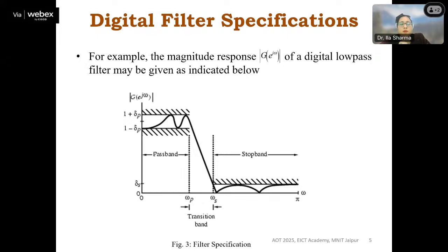And if you observe this designed filter, it has ripple all over the passband and the stop band, so it will not accurately reconstruct the signal or accurately extract the information. So what we want is for this ripple to be zero, whether in the passband or in the stop band. Then only it will behave nearest to the ideal one. So ideally we want del P to be 0 or a minimum value. Similarly, in the stop band we again want no ripples. And the transition band should be a sharp transition, not the slanted one.